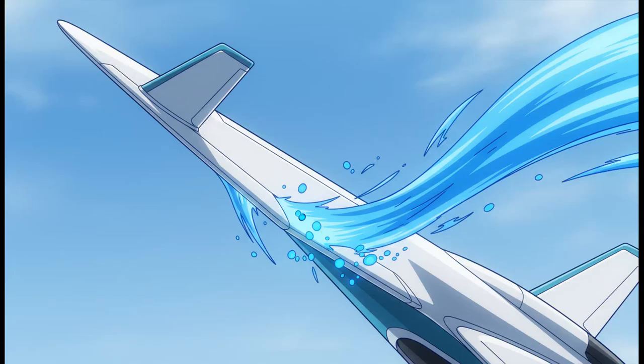Now here is the brilliant exception to our opposite direction rule, anti-servo tabs. You'll find these on planes equipped with a stabilator. That's where the entire horizontal tail moves as one massive piece. Stabilators are almost too effective, making the controls feel dangerously light. To fix that, an anti-servo tab moves in the same direction as the trailing edge of the stabilator. So stabilator goes up, the tab goes further up. It purposefully fights you, making the controls feel heavier so you don't over-control the airplane.